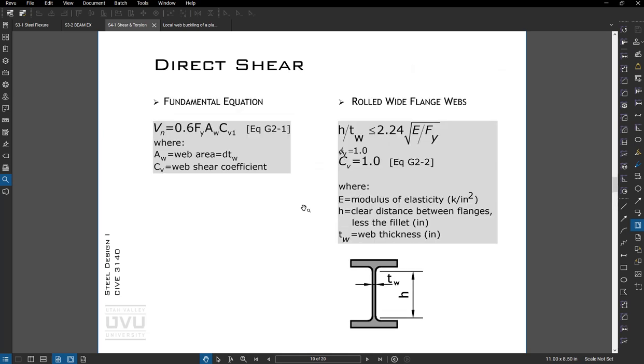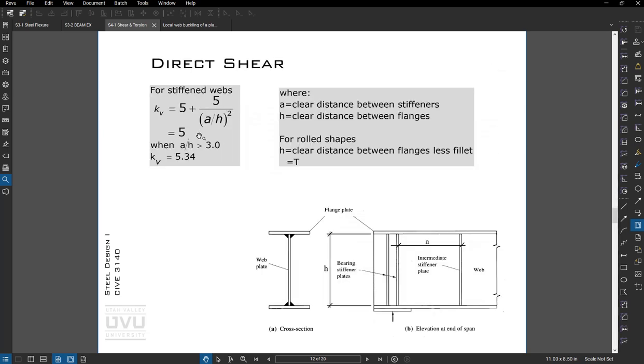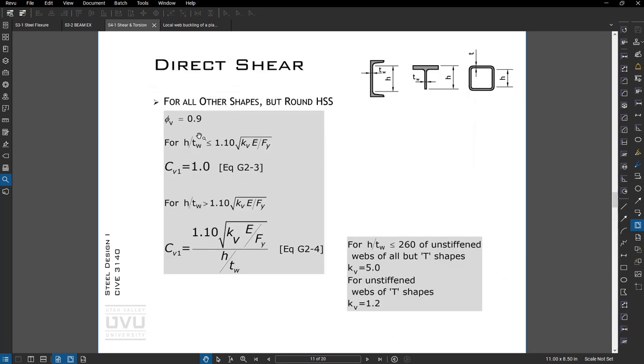All right, sometimes people ask, why is there a 0.6 on the yield strength? Turns out that tension yield is the yield strength we're specifying, and shear yield happens at about 60% of that value. So generally, on any shear equation, you'll see a 0.58, 0.6, maybe 0.55 on the yield. Okay, so more on those equations, and those are things you can get into, and the example covers this more thoroughly.